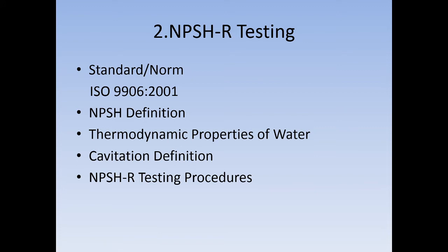In my previous video, we talked about pump performance test according to ISO 9906, and this slide and these presentations continue talking about pumps, but right now we want to talk about NPSH-R. This is a very famous property in the field application of pumps, because without knowing it, we will risk operating our pumps very close to, or already in, the range of cavitation.